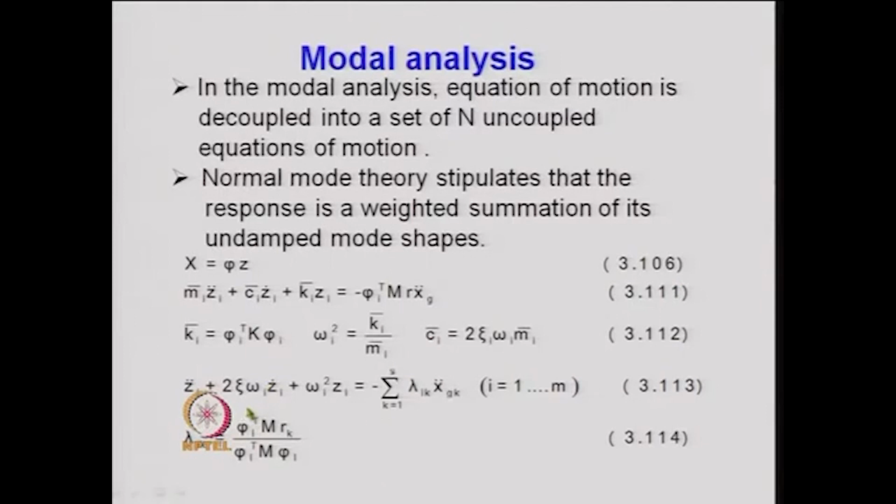Now we can solve these equations written in terms of the generalized coordinate, or modal equations, as single degree of freedom equations, either in the time domain or in the frequency domain. In the time domain again we have options: we can use Duhamel integration, or the Newmark beta method, or any other integration scheme.